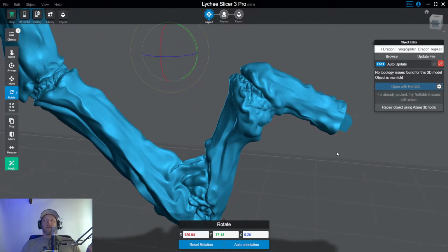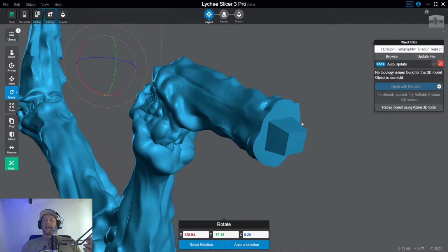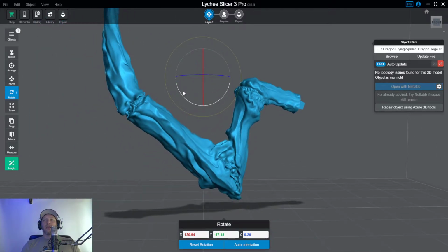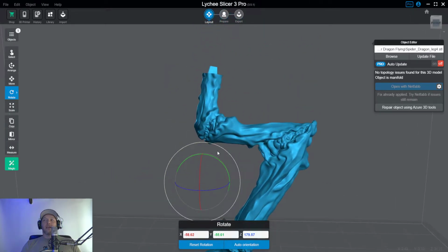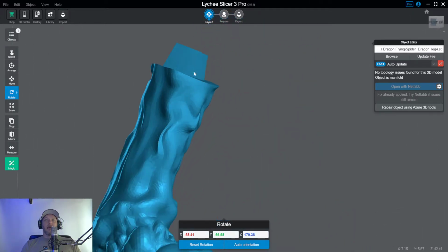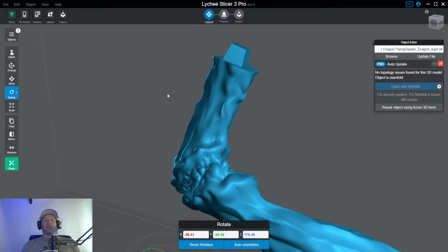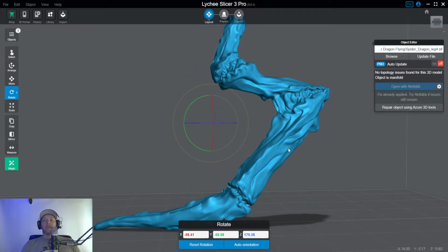Sometimes it's really important. In this case, this leg has a key that goes into a body. It is really, really important for this part to succeed that this key maintains the perfect shape and size. If this sags or doesn't get supported properly, then this key won't fit and this whole part is blown and we have to start over. So what I tend to do is sacrifice everything else in favor of this key not needing supports and being given the perfect opportunity to not be misshapen.